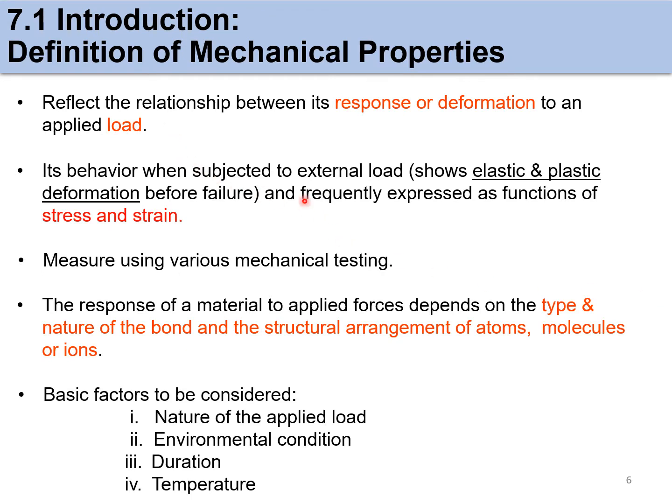So we move to the definition of mechanical properties. If a load is static, what is expected to occur? It reflects the relationship between its response or deformation to an applied load, and its behavior when subjected to external load shows the elastic and plastic deformation before failure, frequently expressed as a function of stress and strain. We measure using various mechanical tests, which can be the tensile test, the impact test, and the flexural test, in order to identify the mechanical properties.